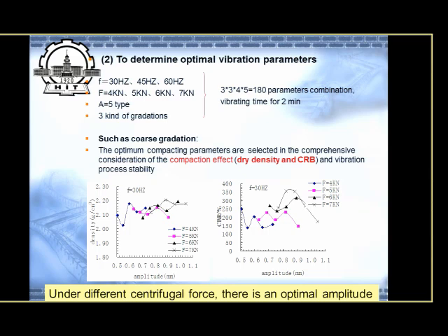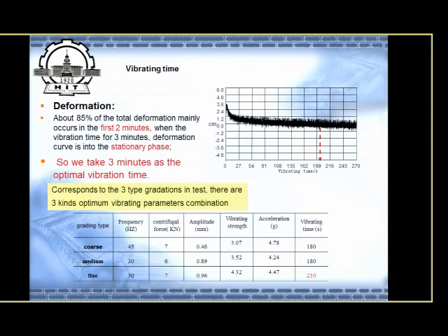We can use those pictures to get the best amplitude and compaction force. Another parameter is the vibrating time, how long we keep it vibrating. This picture shows the vibrating time and space deformation during the compaction.